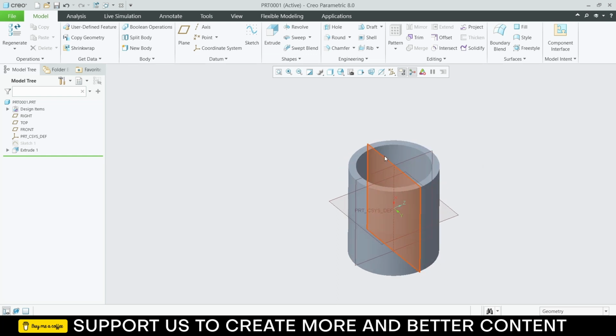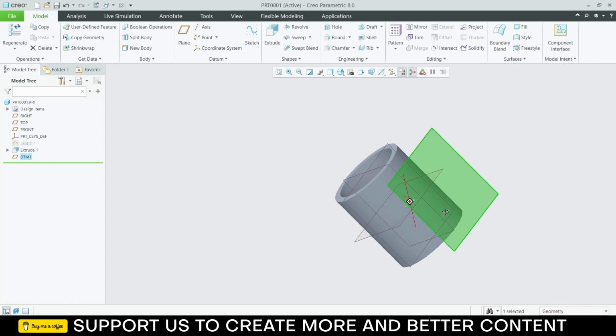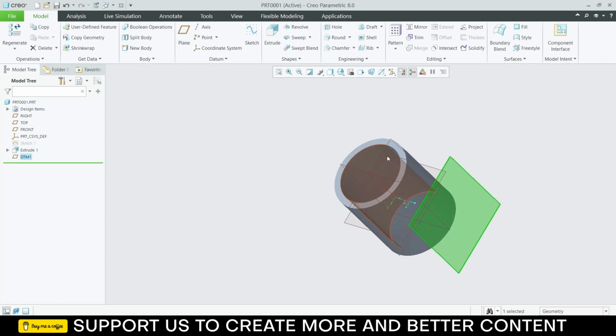Before I do that, select this plane and I will click on the plane. I already selected a plane. Now click on translation, enter the value. In my case 60 is fine. Click OK. Notice a plane is created from this plane at a distance of 60.